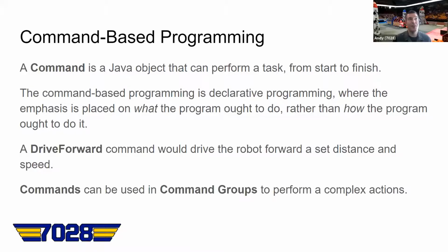And then we can put commands together into command groups. So it could be, walk forward 3 feet and turn off the light. So walk forward 3 feet is one command, turn off the light is another. We can then put those into a group to say we're going to walk forward. We're going to lift our arm asynchronously while we're walking, place our finger above the switch, and then turn the switch off. That might be a sequence of commands or command groups that we would do. We can do the 2 things at once. We can walk forward while we're lifting the arm, and the command group gives us all of that ability to build up those individual pieces into an autonomous action.